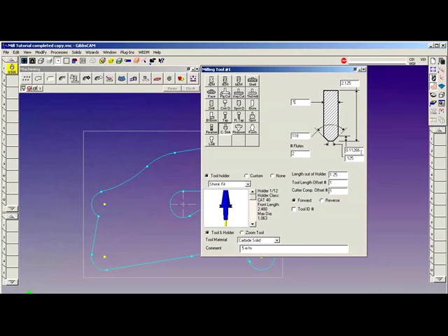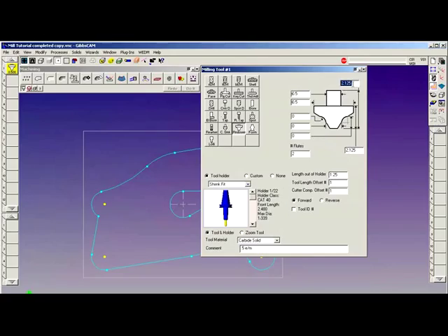The length of the angle will update automatically based on the diameter, pilot size, and angle. A roundover tool is a corner rounding tool. Corner rounding tools are defined by the overall length, shank diameter, body diameter, radius, pilot diameter, distance from touch off to the top of the radius, number of flutes, and the length of the entire tool body.